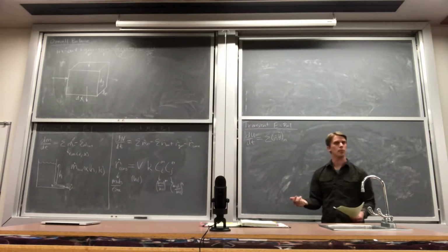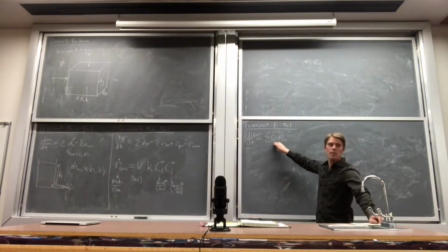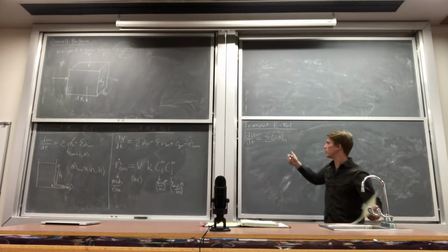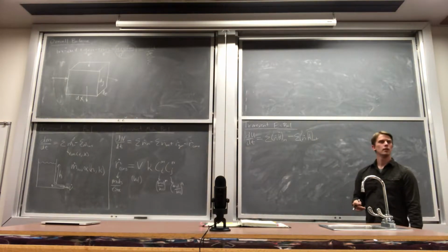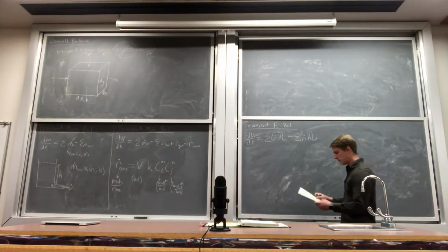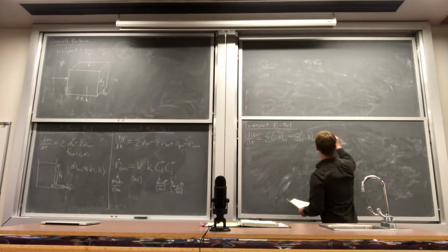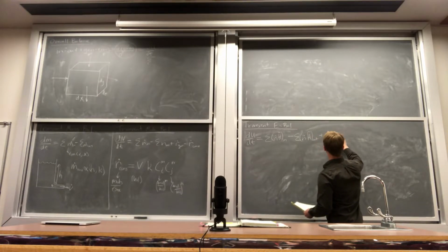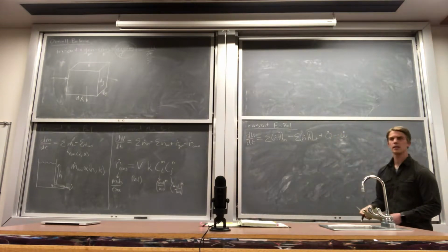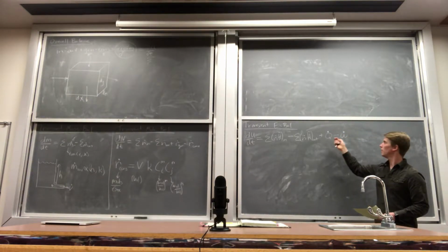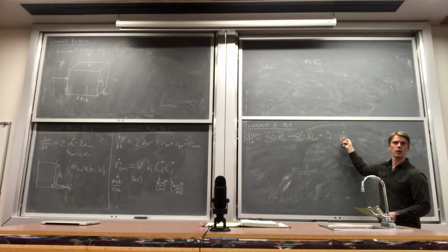Right? So if you're doing a steam tables problem, you'd want to write this as m times h as opposed to n times h. Because it's just the units you have to go with. We have energy leaving the system in the form of mass, right? The energy stored in the bonds, the vibrations, translations, all that. And with heat, we can have heat passing through barriers, whereas mass can't. So we can have heat energy in, and we can be extracting work out.